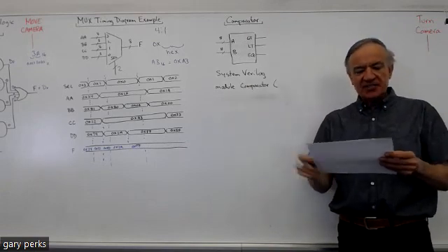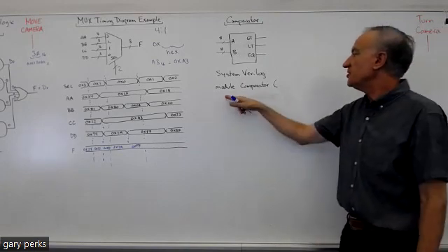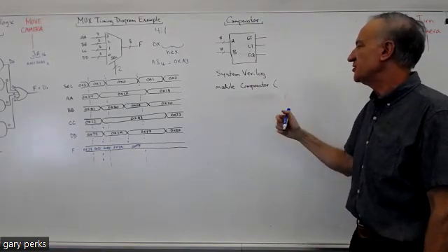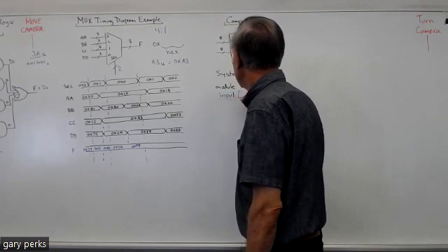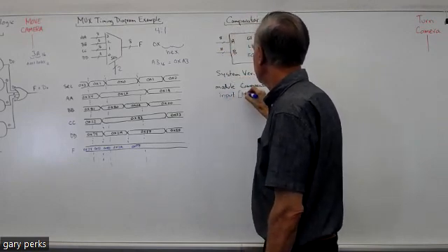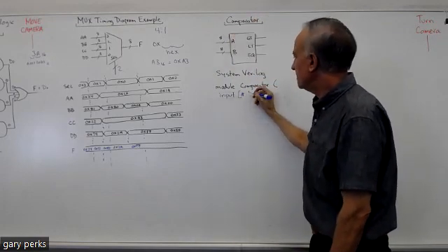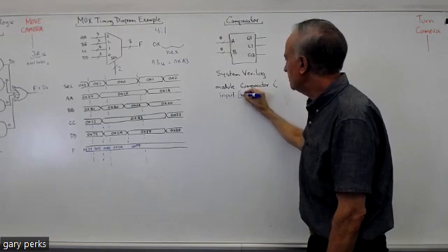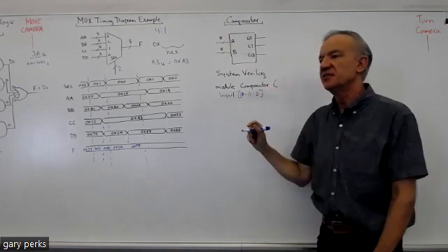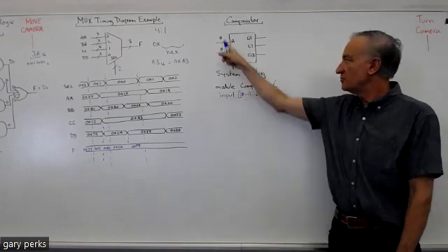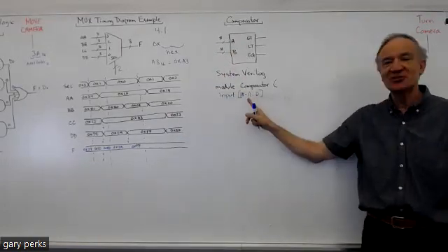First thing is that just like any module, you have to give it a name, and then you're going to define your inputs and outputs just like you've been doing, right? So you have input, and then in brackets, depending on how many bits. Say you had 8 bits, you would put 7 here, right? So you take that number minus 1. I'm just doing it in general terms here. And then the least significant bit is always 0. So you would actually put a number here. I'm just doing it in very general terms, so I'm not confusing anybody. No one's going to write "number sign minus 1."